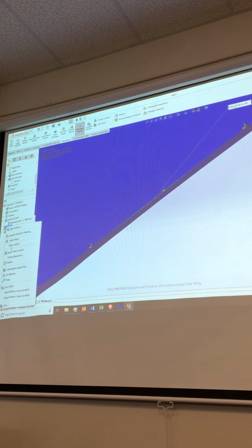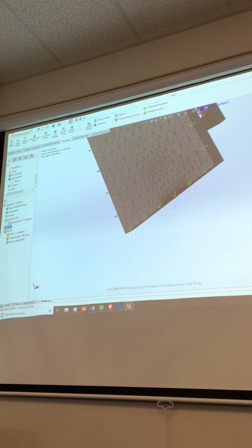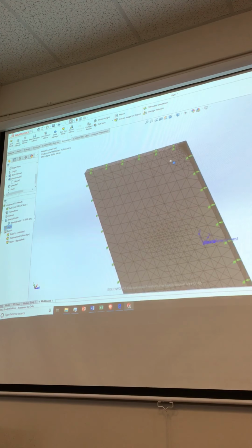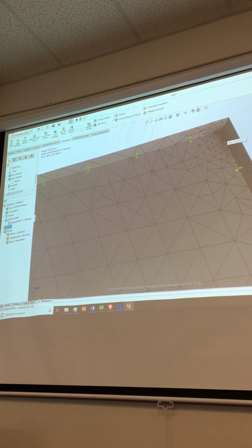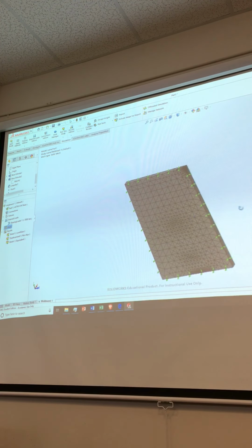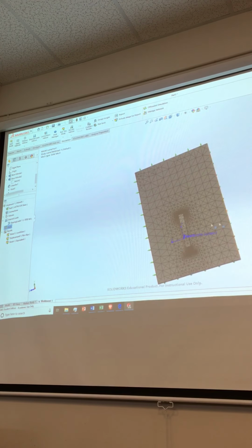It's gonna be refining the mesh, show the mesh, right? It's refining the dickens out of that bottom. The top is actually looking pretty good here. I got a little bit of mess over in this corner, which is because of this displacement constraint in here. But that one's probably not bothering me pretty much. The others are looking pretty good.